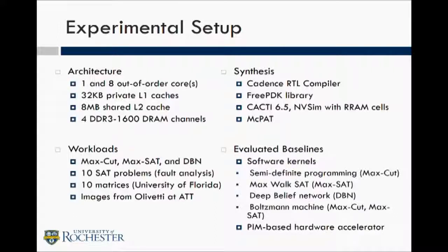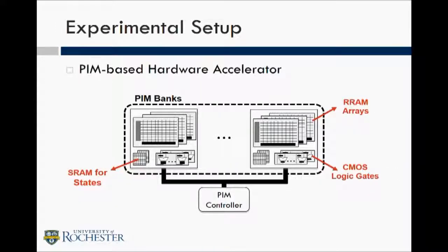A real strong baseline, if you're doing analog computing with RRAM, the real strong baseline is something that looks like this. So this is processing in memory. PIM, it's been around, it was invented earlier than my birth, right? This is like 40 years old. Putting small digital logic gates right next to small arrays and doing computation within memory is not a new idea. This is well known. RRAM is not our invention. So if you're getting benefits because of RRAM's density, then that's great, but that's not necessarily a contribution.